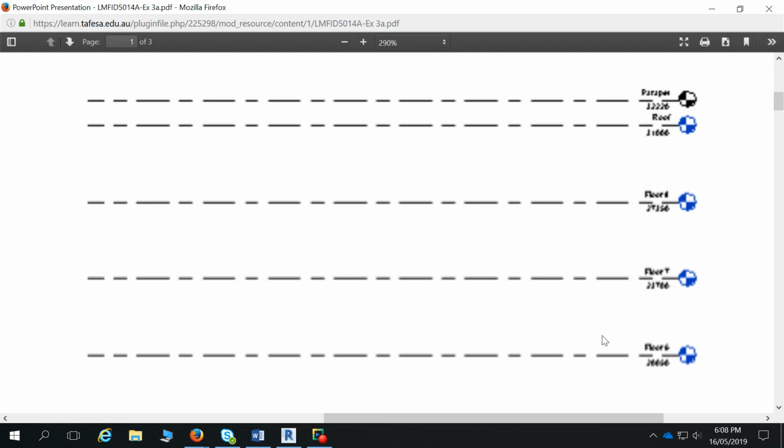Again, I don't know why we do that, particularly when the software is set up to do it. It's probably just because that's how we've always done it, and we've had to make Revit adapt. There's a few issues when you do it this way: you end up with a floor plan, a ceiling plan, and a structural plan for each level you draw, unless you untick something, and it does clog up your project browser, which makes it a bit harder to read.